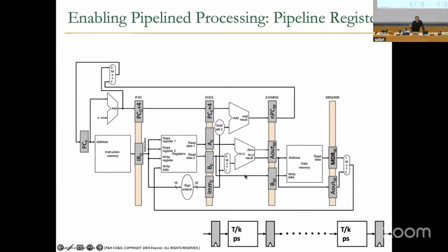Okay, so I could keep doing this essentially. Here you calculate the next PC based on PC plus 4 and sign extend immediate left shifted. And then you store it at the end of the execute stage, in the execute/mem stage registers. ALU output is also stored over here. And look at, there's curiously something called B over here.